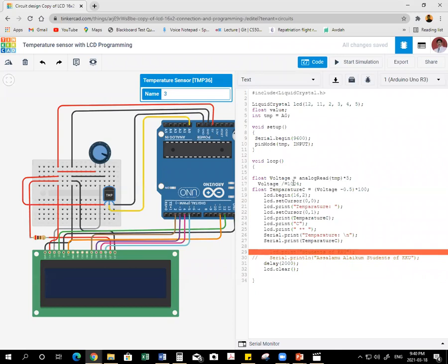Clearly it is mentioned here, we are multiplying by 5 and dividing by 1024, so it is called scaling. No, it's not scaling, it's converting, because we are converting the millivolts to the bits value. Now the voltage we are giving is not exact, based upon the temperature sensor company data sheet, what the company manufacturer will give. Based upon that, it is minus 0.5 volts.